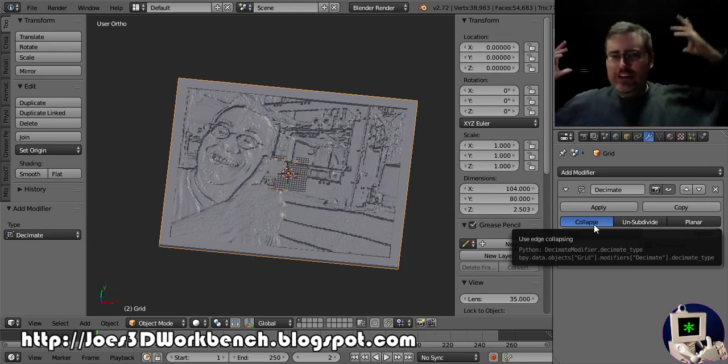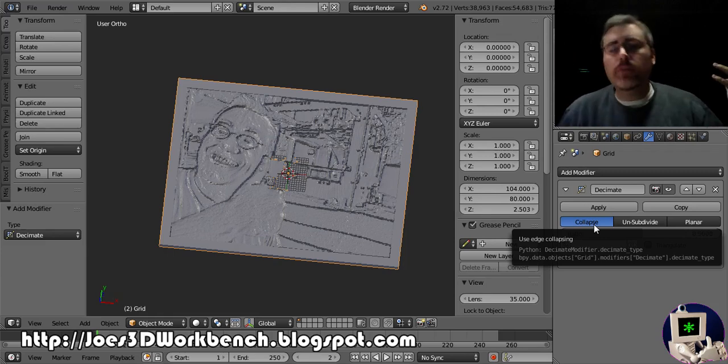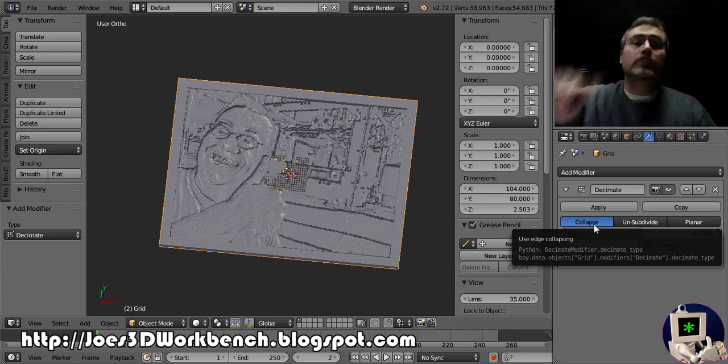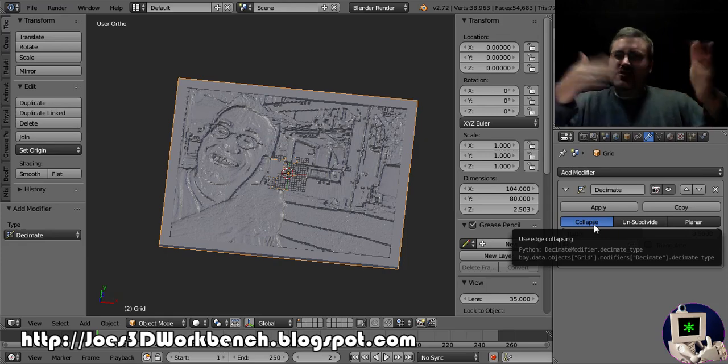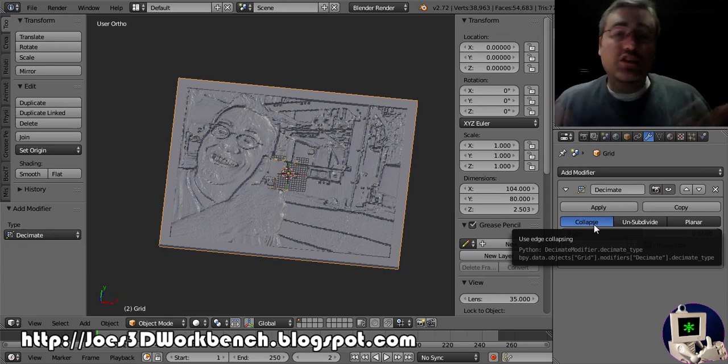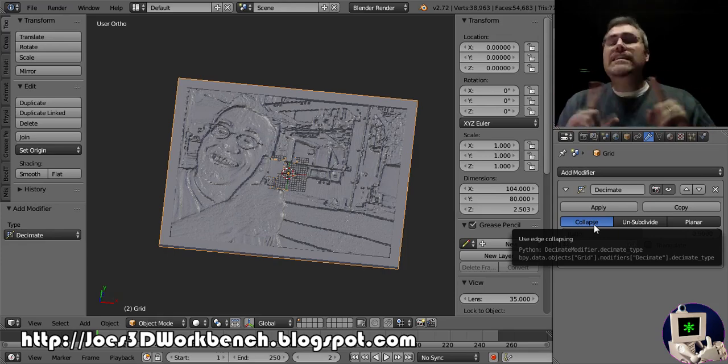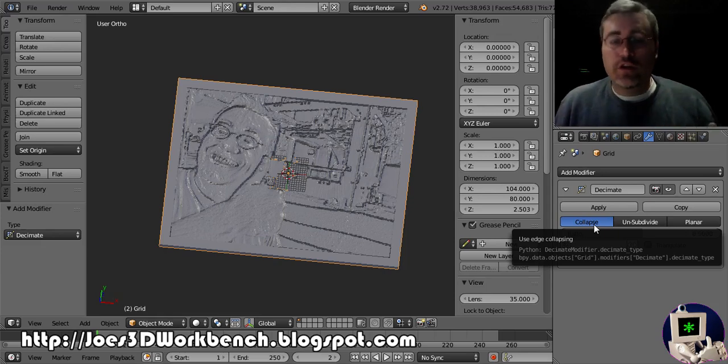If there's trees in the background, they are terrible for lithophanes, because there are all sorts of color depths in there. We'll just select the trees, decimate just those, and they'll still be up and down, but they'll be a lot less up and down. Your slicer won't choke on it as hard. I recommend using that trick even if you've used another piece of software to create these lithophanes.